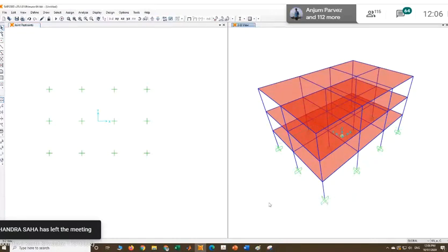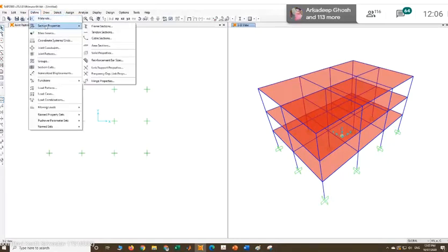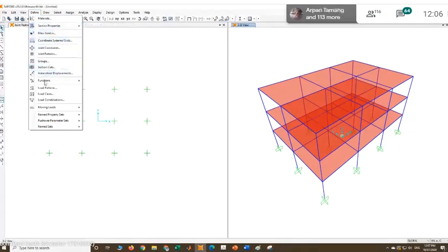We have assigned beam column as per our requirement. Now we have applied dead load, and we need not calculate it manually and then apply to the structure. Now you need to apply some live load. For that, we first need to create the loads we are going to assign. We have created material and section properties, and there are various other commands, but the important commands I will highlight for now. Load patterns: what load we are going to apply.